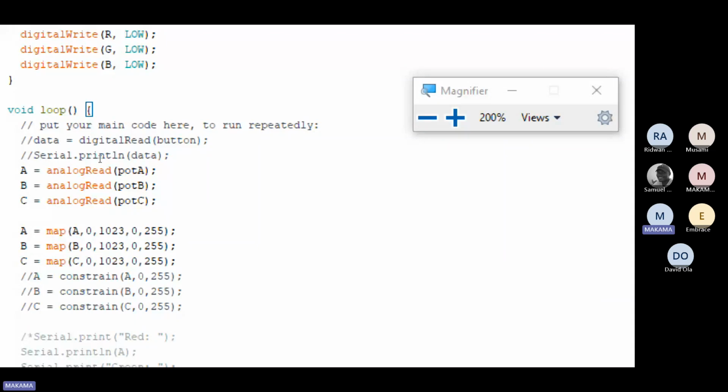You can read a value between 0 to 5 volt. Even if the voltage is kind of low, maybe around 1.5 or 2.5, you can read that analog voltage there. But if you use digital read in the place where you used to use analog read, you know what will happen? It will just make a conclusion. That conclusion is that any voltage from 0 to 2.5 will be counted as 0. Any voltage from 2.5 to 5 volt will be counted as high, which is 1.